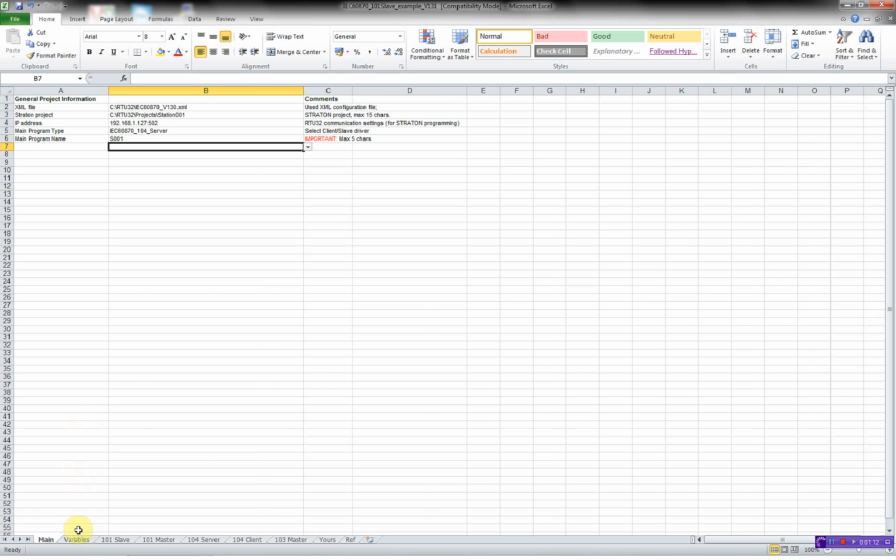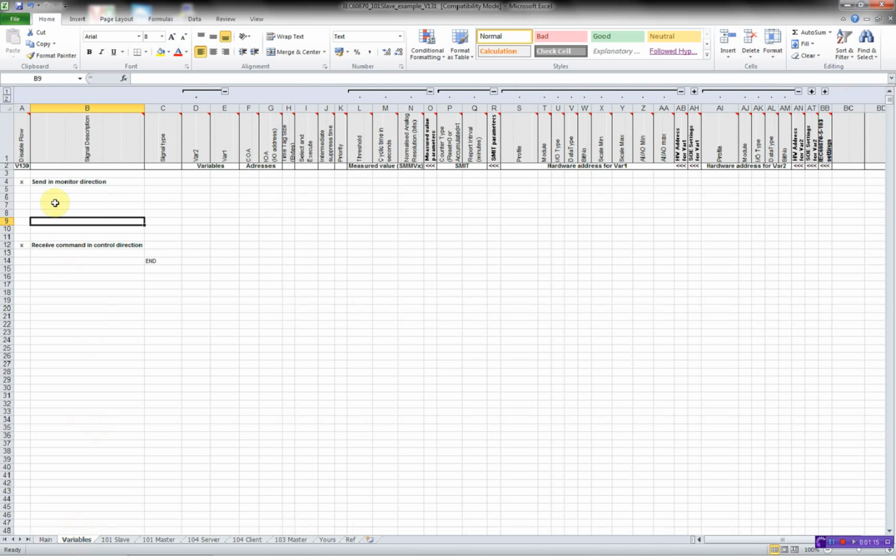Next thing to do is to define my different data points. That is single point, double points, etc. Here I'll start by defining a local remote door switch, AC supply monitor, DC supply monitor, valve position, a flow, and a temperature, and we also have a controllable valve control. Then I have to define my signal type.